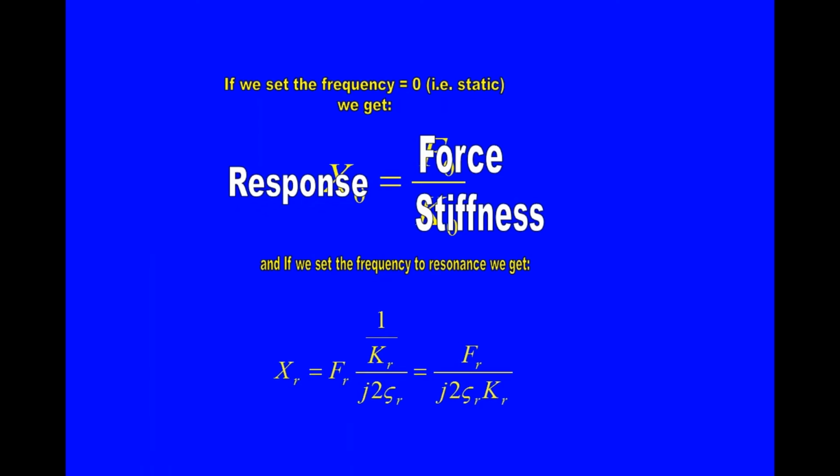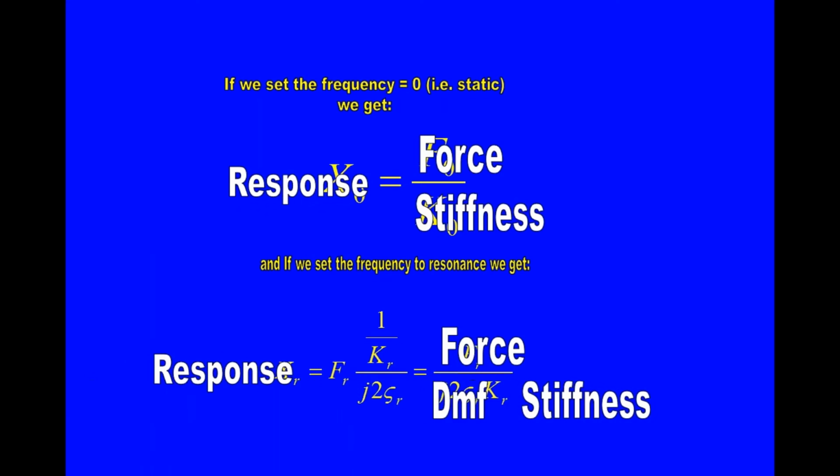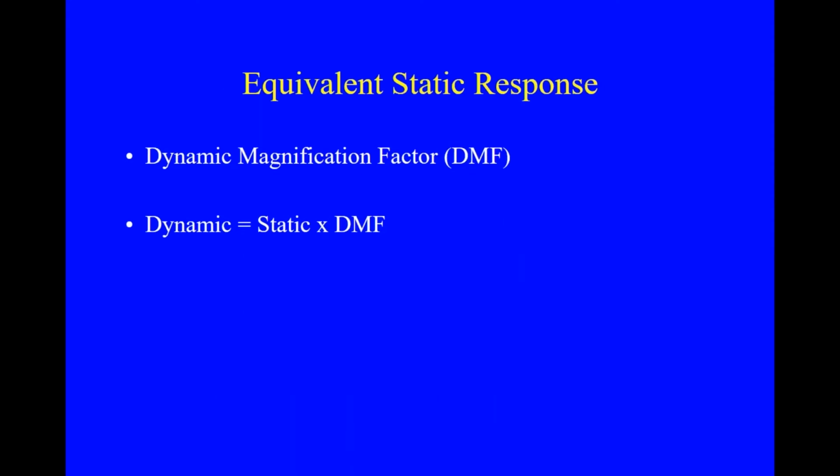we reverse engineer it. If we've got this mechanism coming from fracture mechanics, we can take those fracture mechanics equations to pieces and say, okay, now we are measuring the nonlinear damping characteristic of a structure, and it is telling us about the energy dissipation going on in that structure. It's telling us how it's occurring, what sort of mechanism is causing that energy dissipation.